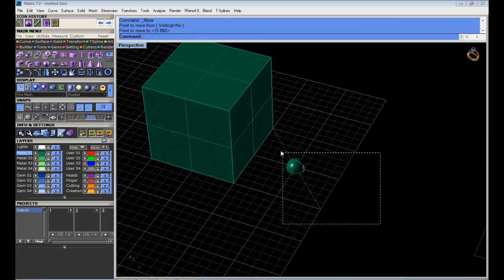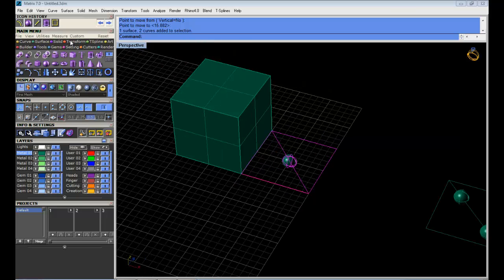now we need to select it again, and we're going to rotate. We're going to do it in rotate 3D, which is slightly more difficult, but it's worth it. Rotate 3D, and now it's asking us for the rotation axis. Just mind that this is like the movement of a door. Okay, so the rotation axis in this case is going to be from this endpoint to that endpoint, or from this endpoint to that point. Doesn't really matter. We just need to select the axis.